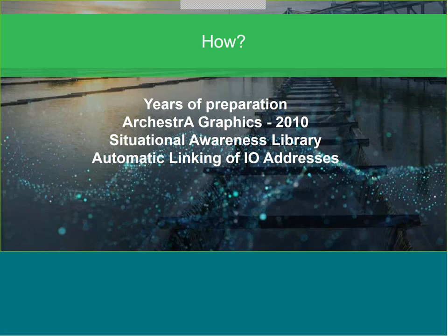They've also introduced things like automatic linking of I/O addresses, so that allows you to import a load of your templates, a load of your instances and objects, loads of your I/O, and you can link it to specific topic names. So if you have things like symbolic references in your PLC, so you have one of the more modern type controllers, because that features things like UDTs, it's very similar to the object-based design that you'd set up inside a system platform. So when you compare the two and you set them up in a very similar fashion, it's very, very easy to link that I/O address. And there's lots of detail on how we achieve that.